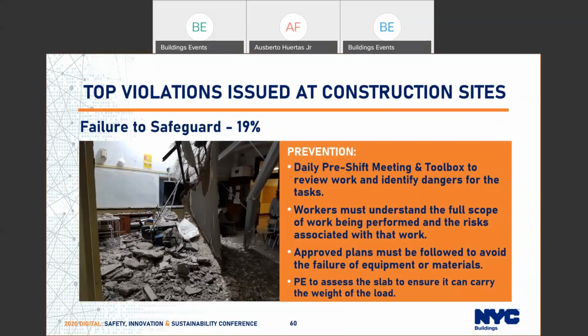Before placing heavy equipment on a roof or deck, the area should have been structurally assessed to ensure it could carry the additional load. Additional preventative measures should have included a daily pre-shift meeting and toolbox talk to review work and identify dangers. Workers must understand the full scope of work being performed and the risks associated with that work. Approved plans must be followed to avoid the failure of equipment or materials. Professional engineers should have assessed the slab to ensure it can carry the weight of the load.